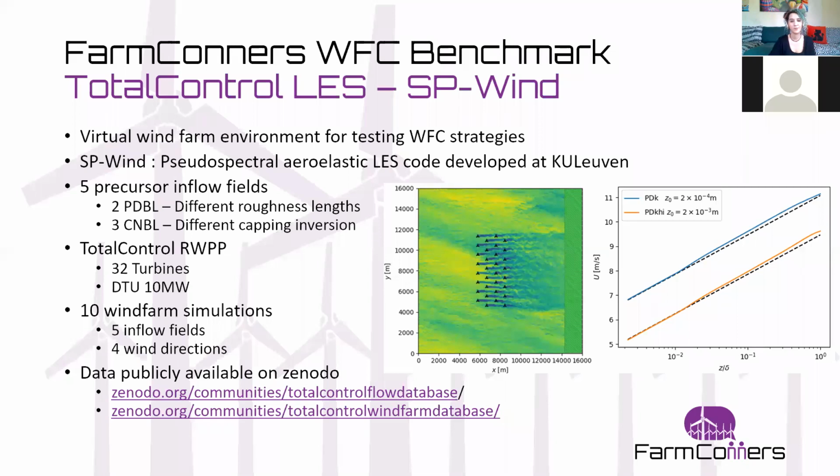Okay, so one of the main goals in the Total Control research project is the development of a virtual wind farm environment for the testing of wind farm control strategies. To this end, at KU Leuven, we have developed SP-Wind, a pseudo-spectral aeroelastic large eddy simulation code. Using SP-Wind, we have developed 5 different precursor inflow fields to cover different atmospheric boundary conditions for wind farm operation.